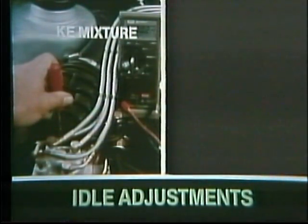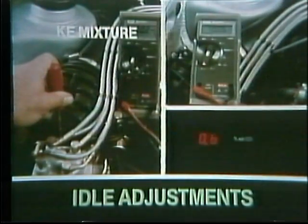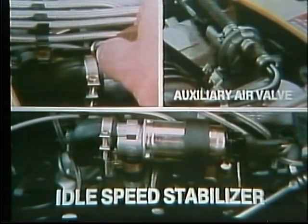If idle adjustments are necessary, KE mixture is adjusted according to 2 specifications: milliamps to the pressure actuator and CO readings on the exhaust gas analyzer. Besides adjusting mixture, you may adjust idle RPM when the engine has an auxiliary air valve. But when the engine has an idle speed stabilizer, as on most KE Jetronic systems, turning the idle speed screw will not change idle RPM.